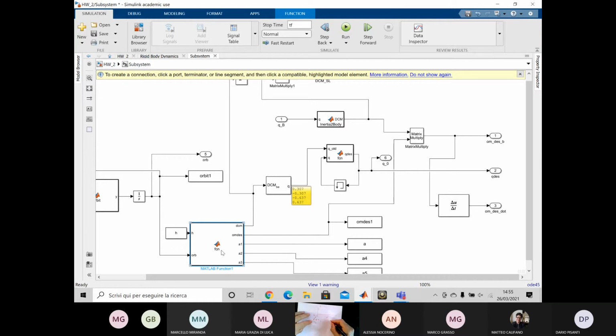And we think that that quaternion, Q0, corresponds to a theta of pi, right? And an eigenaxis of, what did you say? 0, 0, 1. 0, 0, 1, yeah. Okay. So this is how my spacecraft should start, with the body axis aligned with A1, 2, and 3. And I should be able to represent that orientation starting from the nominal. The nominal one is basically with the body axis aligned with the inertial one, right?